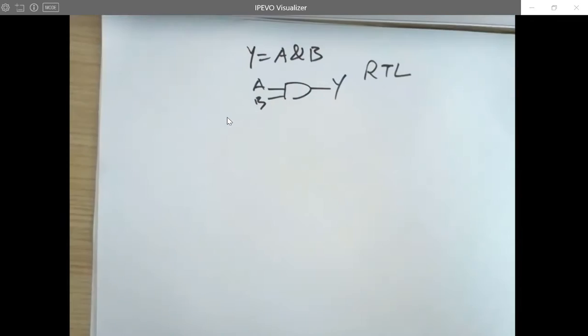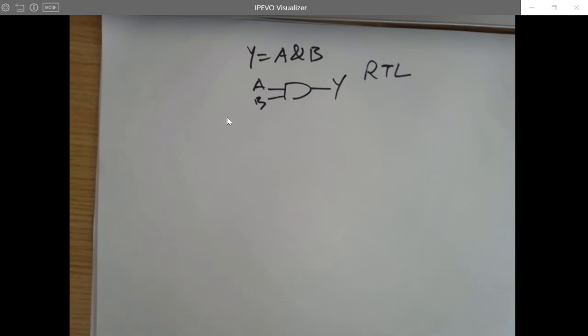So here's a question. We learned about Flash, right? Flash uses a floating gate to be programmed. So what's the voltage to program it? 20 volts, 25 volts sometimes, just high voltage. But for small technologies like 40 nanometer, if you apply 20 volts, it's going to blow up everything. But still, when we are programming the ESP32, we can still store the program in there, and we can still run it, right? Why is that?